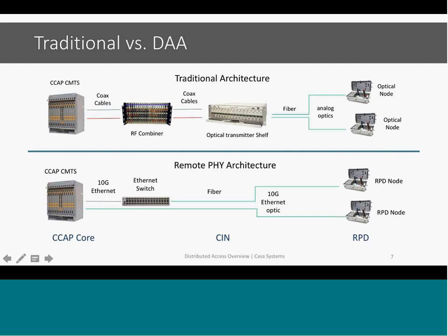The things we'll talk about and give a little bit more on in the presentation: typically other parts are brought in through your RF combiners. So you could have your narrowcast QAM or your broadcast QAM or other devices that transmit the QAM signals and are managed independently. One of the things you'll start to see become more relevant is that now I can combine things on the IP side and deliver just a glass with all of my spectrum contained within it, and that terminates on the RPD, and then it's up converted back to coax and delivered over the last 10 feet.